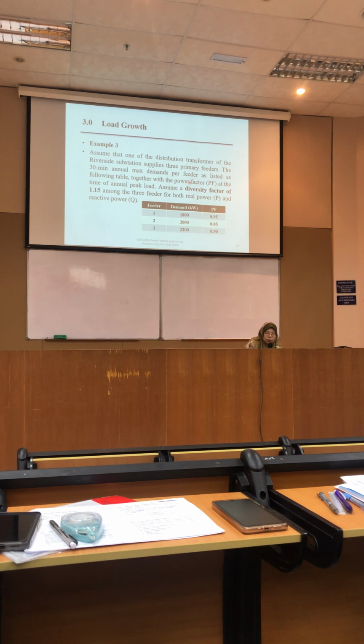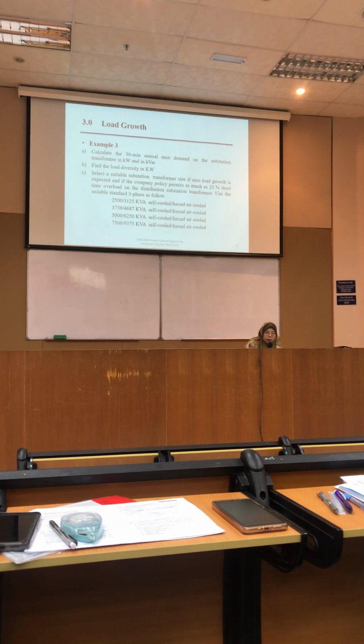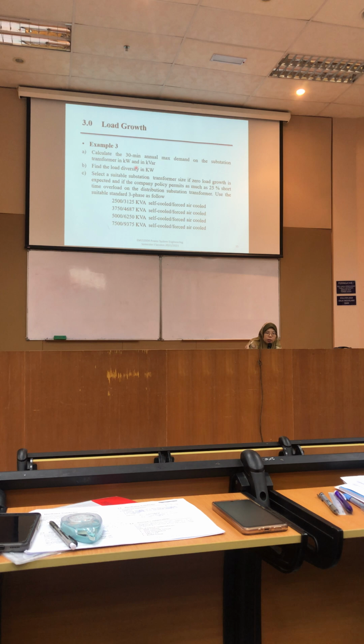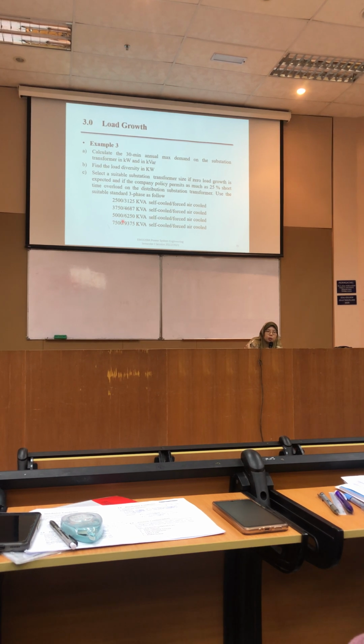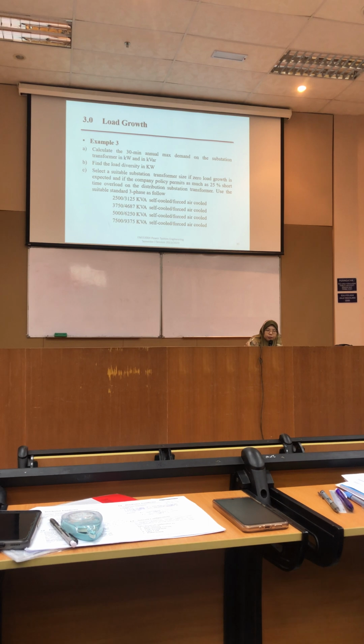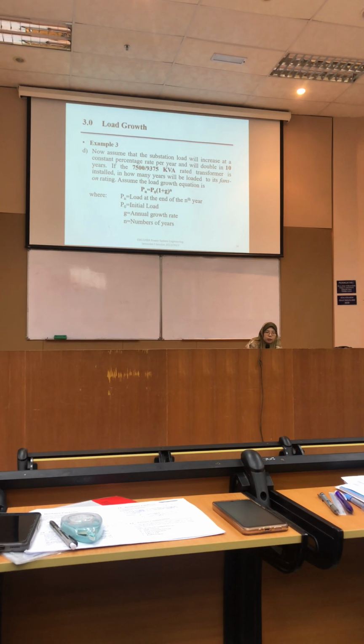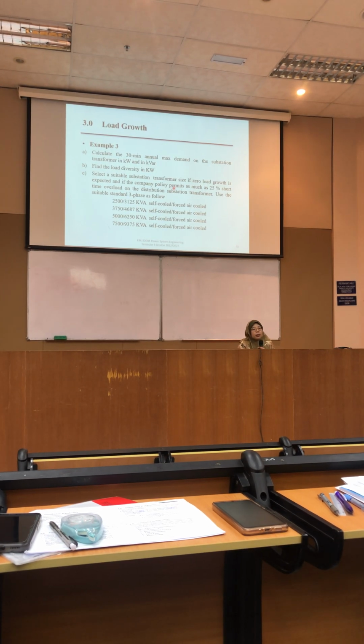Okay, so we are going to calculate the 30-minute annual maximum demand, kilowatt and kVAR, the load diversity, and determine which one of the transformers is suitable for the load. Okay, the company policy permits as much as 25% short time overload.